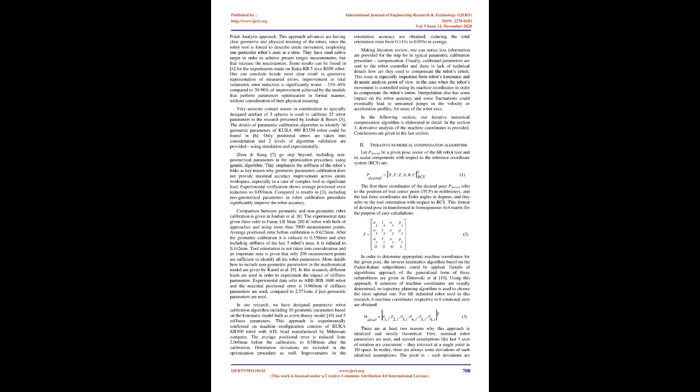Wang et al. [3], for example, have developed a model to calibrate 27 DH robot parameters, measuring a set of positions that follow a circle path. Their results are experimentally confirmed on a Hyundai HA06 robot, reducing the average volumetric positional error from 3.657 mm before the calibration to 0.129 mm after the calibration. Orientation error expressed by the Euler angles is reduced from 0.330, 0.6720, 1.400 on average, to 0.0090, 0.0170, 0.013 after the calibration.